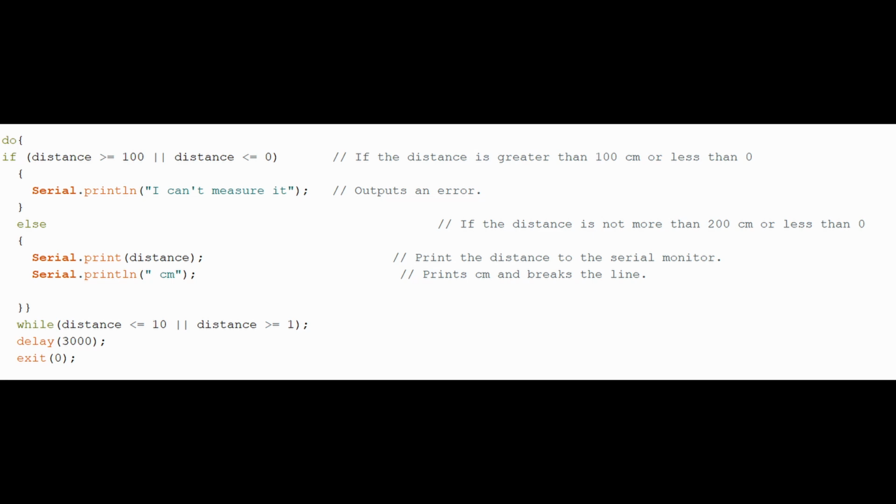It was supposed to activate the ultrasonic sensor as the next step when the button was pressed. But in the do-while loop I wrote, the do loop was activated immediately, so it could not exit the loop and only displayed the result of the ultrasonic sensor. I tried to use a for loop, but I had trouble with this for loop also. So, unfortunately, I couldn't get the ultrasonic sensor and timer to work together.